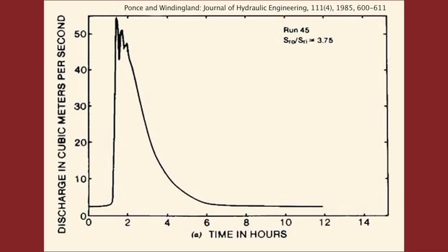The kinematic wave equation is nonlinear because the celerity varies with the flow. This nonlinear property leads to a steepening tendency of the kinematic wave. Due to the steepening, overland flow analytical solutions of the kinematic wave have a tendency to develop a shock.